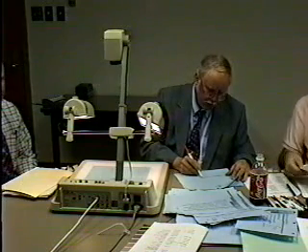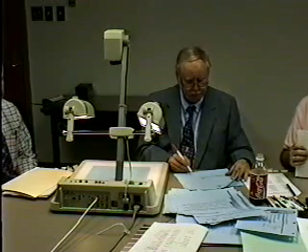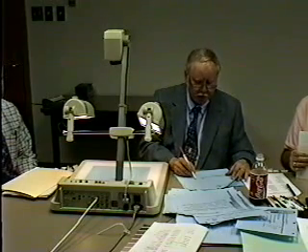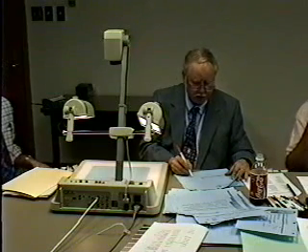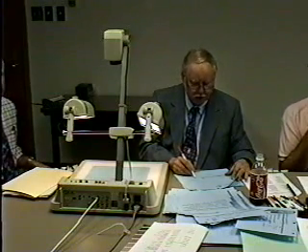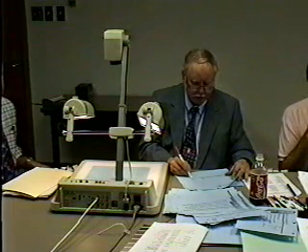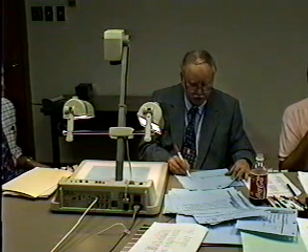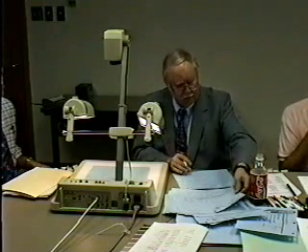For instance, if you show the load P at an eccentricity e off of the neutral axis, then you get some sigma equals P over A stresses, and you have to add them with some sigma equals Mc over I stresses, some combined stresses. That's a sheet I'll come back to if we've got a little time.